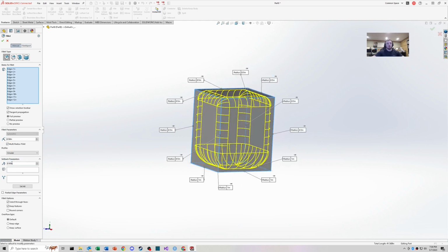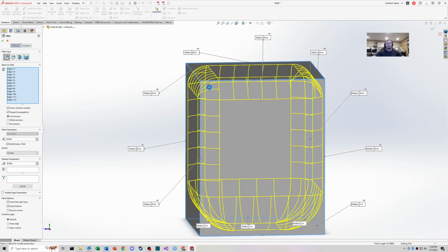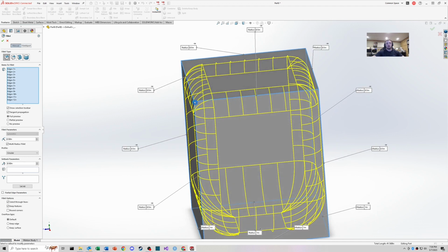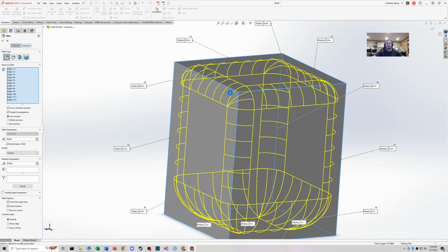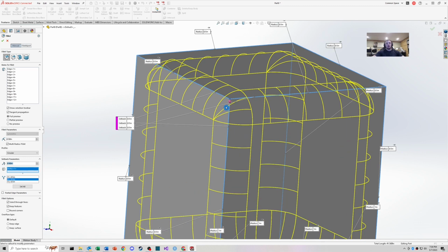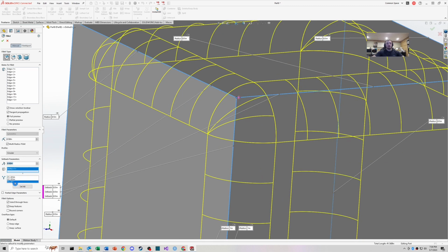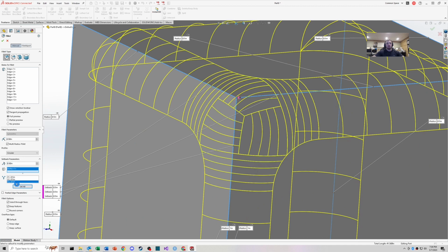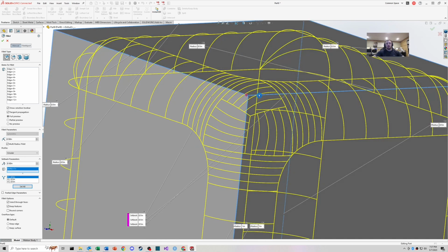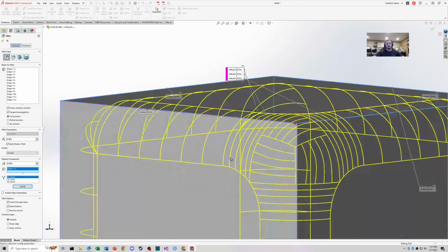And then one more thing to point out with fillets, there is this setback parameter, which allows you to define basically a blend of 3 intersections. So if I have 3 fillets intersecting in a corner like this, I can make a little bit softer corner at that intersection. So I'll show you how this works here by selecting an intersection like that, and then it is looking for an input of how far is the setback for each direction that you'd like to start blending those lines. So there the preview goes, and you can see there's kind of like this radius starting here and also this way along that edge that starts to soften that corner.